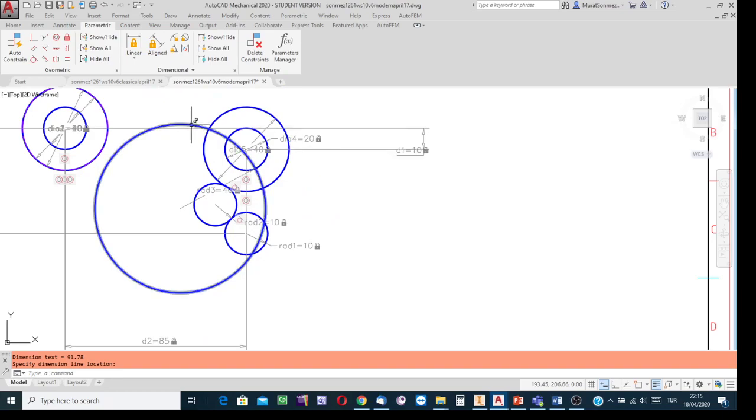If I input a tangency constraint, and this circle relative to the available one is at the wrong side, then this circle will be tangent to the indicated one at the wrong side. In such a case, the thing to do is apply the move process. Or, this may be easier, make a click at any point along the circle.